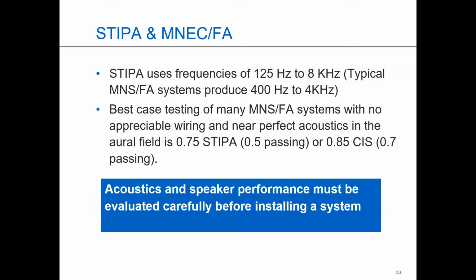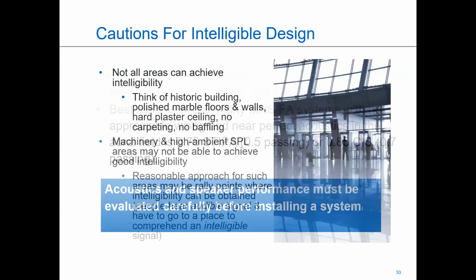high fidelity. So in our world, in the Eaton world, all of our speakers on our legacy products, which weren't high fidelity, have been recreated in a high fidelity version. So I don't really need to go through the STIPA or the NFPA requirements to produce the tones, just to tell you that they're high fidelity speakers that have a broad frequency response for, like, say, from 300 to 8,000 cycles. That's what you're really looking to hear.